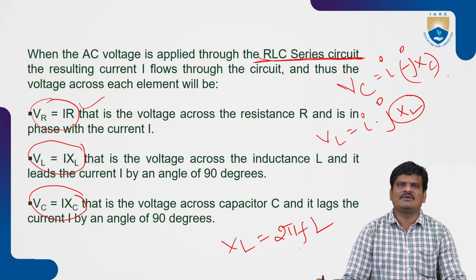And coming to the property of this particular capacitor, current will always lead the value of voltage by 90 degrees. If it is a pure inductor, the current lags. So all these cases where the current is lagging, leading, or in phase are represented with respect to their own angles like 90 degrees and 0 degrees. When we are using pure elements like a pure resistor, pure inductor and pure capacitor, the angles may vary but the nature of the inductor and capacitor remains the same.